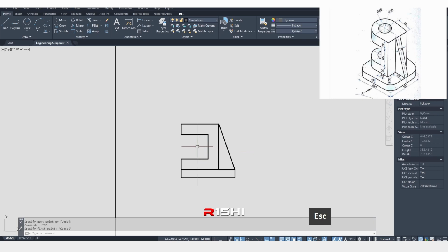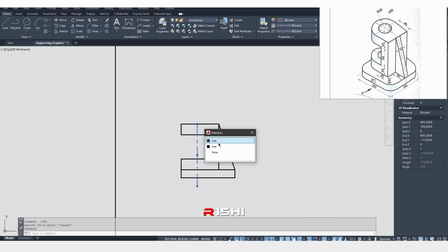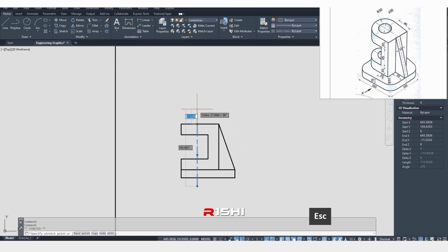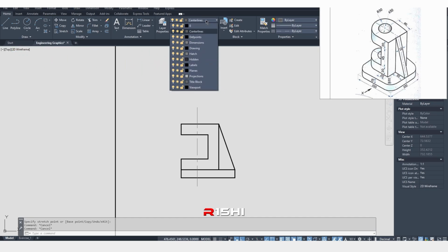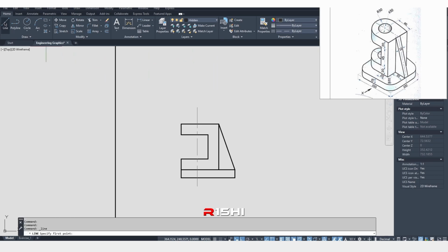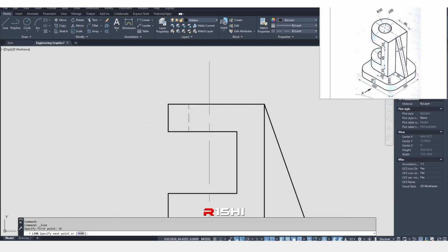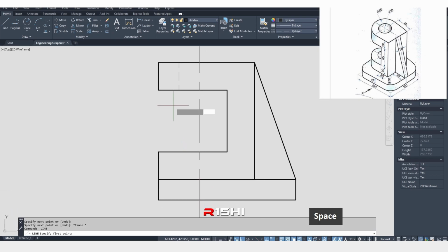I just want to extend my line this way, right? Now I want to draw hidden lines. I have different options. What I'm going to use is go to hidden line command, go to line. We know the diameter is 30, that means radius is 15. I will hover my mouse on this intersection and then give this direction, type in 15. Our line will start from there. When you get the perpendicular object snap over here, click. Then I will press escape and again press enter to start the same command.